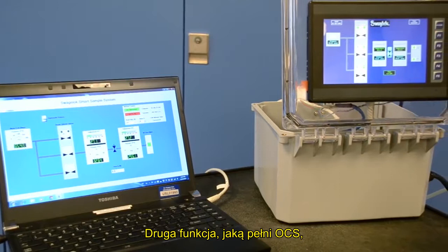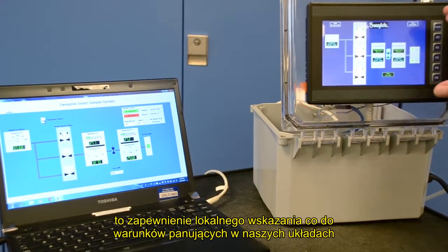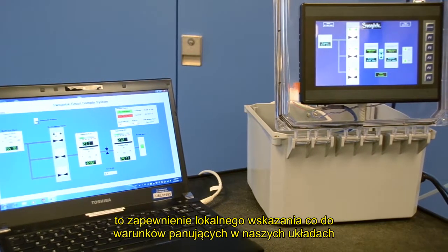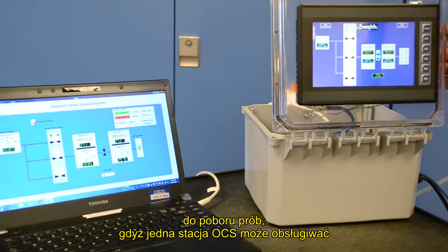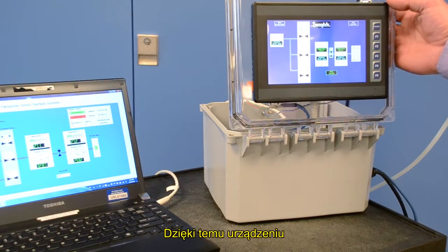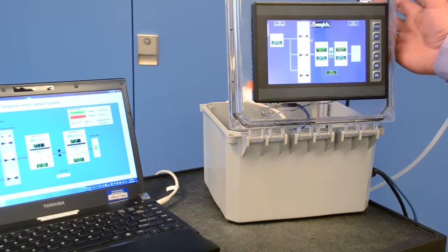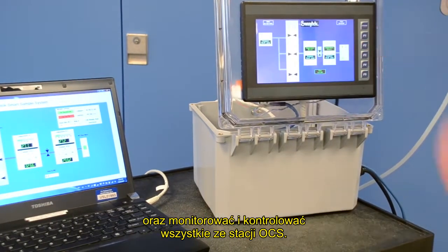The second role that the operator control station fills is to provide a local indication of the conditions of your sample systems. Now, I say sample systems because one operator control station can manage up to 25 Swagelok automated fluid systems. So with one of these in your analyzer shelter, you could have 25 sample systems at that location, all of them being monitored and even controlled from the operator control station.